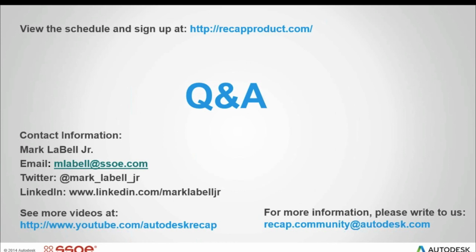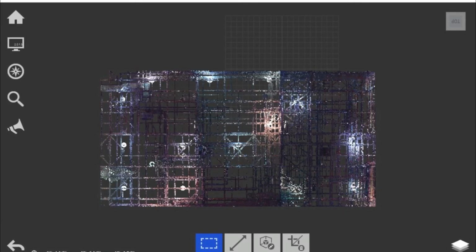And similarly to that, if you click on something that's well outside your plane, they're asking if that will be thrown out, or if that then includes it in the plane. It does actually. The one thing I didn't show as part of the process is I always, because of the time we have here, make sure to rotate around after I select a plane to make sure it's not off at some crazy angle, like I had mentioned with a ramp.